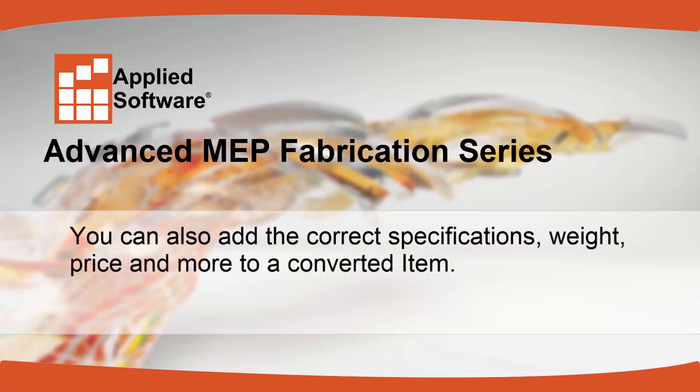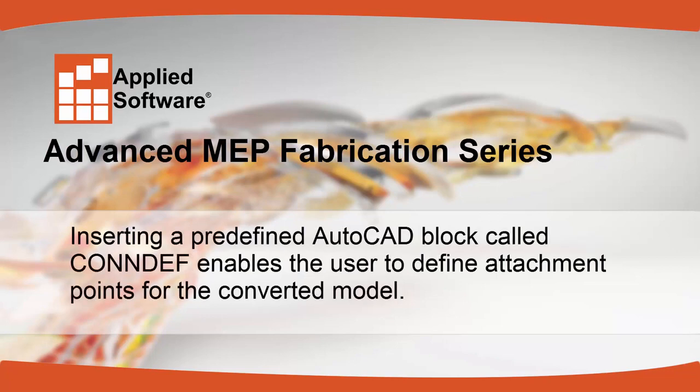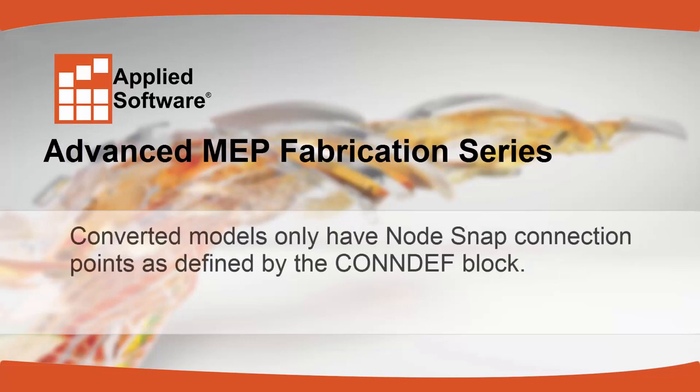You can also add the correct specifications, weight, price, and more to a converted item. You have the ability to connect the correct size pipe, duct, or cable tray to the item. Inserting a predefined AutoCAD block called ConDef enables the user to define attachment points for the converted model. Attributes within the ConDef block control the type, shape, size, and location of connections to the item.